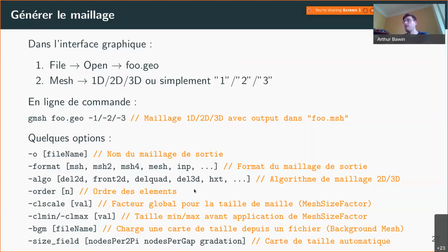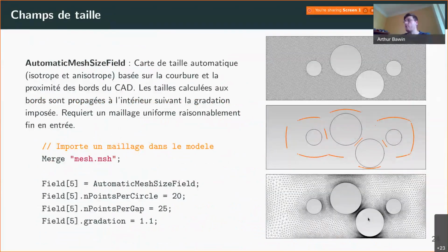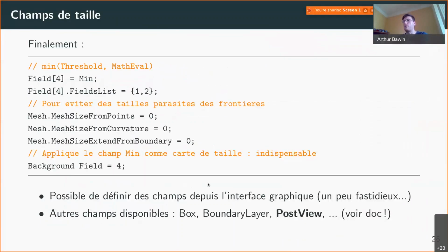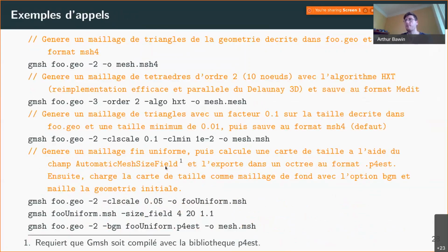For example, this is a quite finely graded mesh, which means, how do you call that? The ratio of two adjacent triangles is not that big. You don't allow triangles to grow very fast as you go away from the boundary. That's what I mean. It's called gradation. So a couple of calls, checking the time.